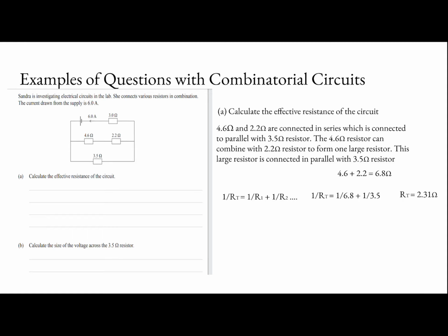So basically, like I said, the students are splitting into two different ways. So pathway 1, there would be two different classrooms, and these two different classrooms add up to create the total resistance for pathway 1. And the total resistance of pathway 1 is what we use in our calculations. I forgot to add the 3 ohm resistor. The 3 ohm resistor is connected in series, so it's simply added on. So 2.31 plus 3 is 5.31 ohms.